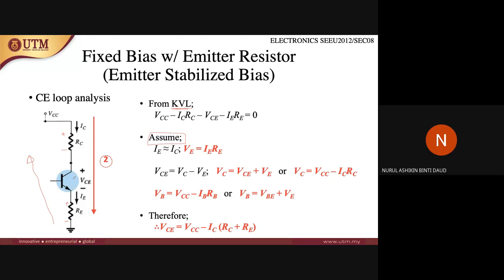So we assume the current IE is almost equal to IC. As we assume this, the value of VE here is equal to IE RE.